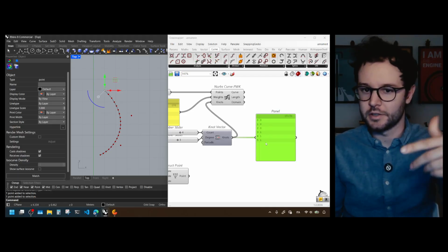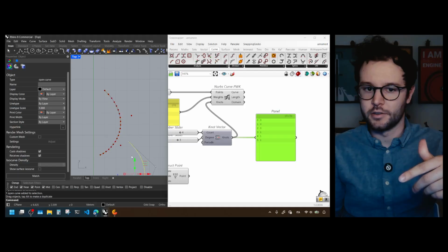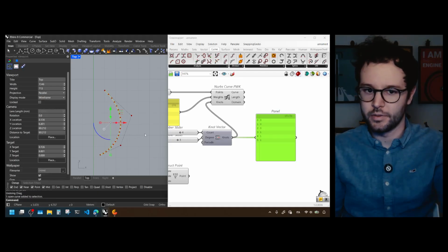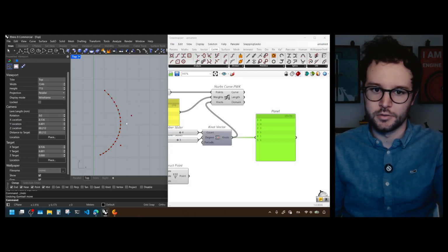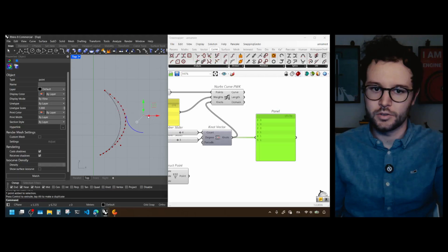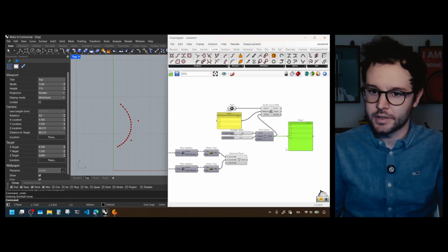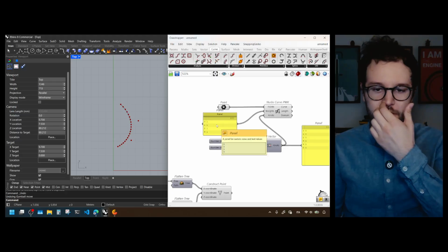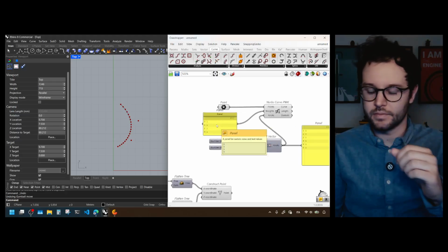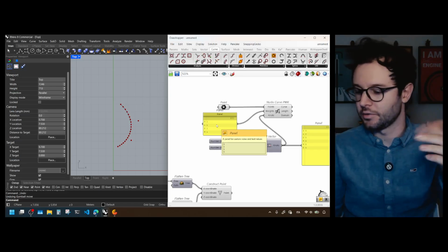The others are not points which are used to pass through, but just control points that are used to control the shape of the curve. So these are all the parameters of a NURBS, and these weights are the reason why the function is called rational or non-rational.